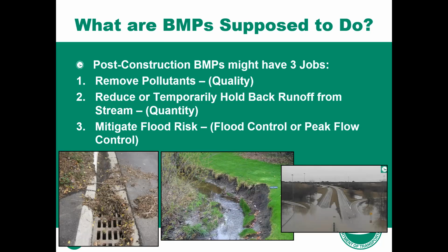So all of that flood risk aspect of things, which some people call quantity, some people call flood control, that's all mandated or controlled by the locals. So not at the state level, not for Ohio EPA and ODOT. So most of the BMPs, all of the BMPs I'm talking about today are quality or quality and quantity BMPs. Look at getting the TSS down, improving the quality, or holding back runoff to decrease the potential for hydromodification. I'm not getting into peak flow control, which is that third thing. So it's important to think about those 3 things when you're thinking about BMPs, because some of these ODOT BMPs do 1 or 2 of these 3 jobs that most of our post-construction BMPs might have.